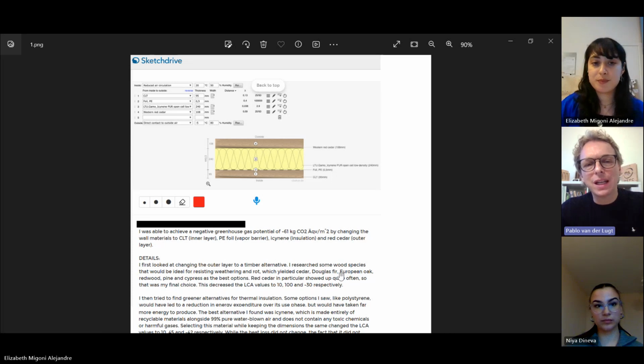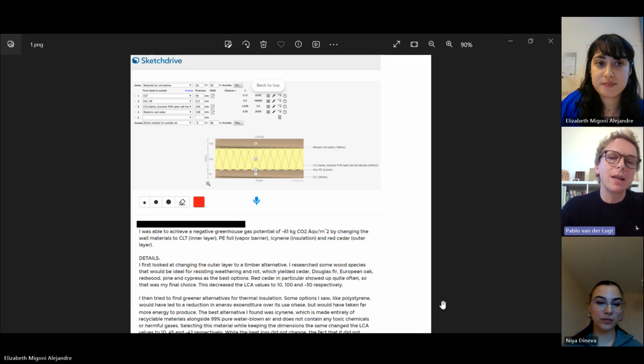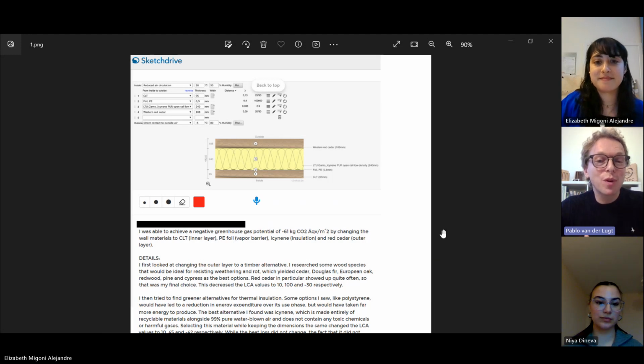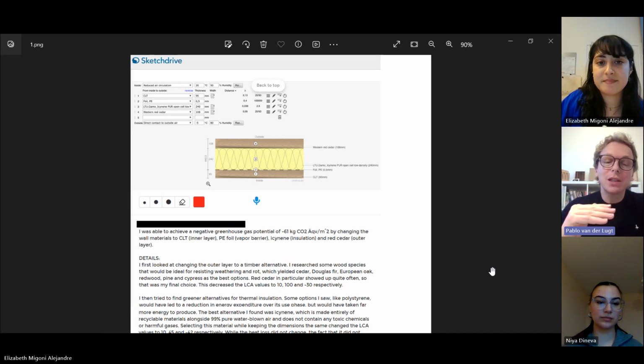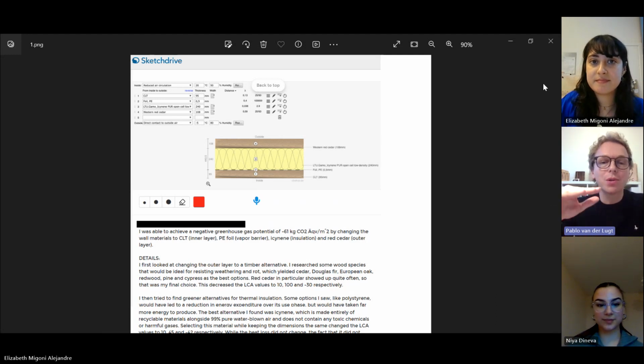And of course, you need this, and of course, it could add a little. This is also a material choice that can maybe add up to the carbon footprint. And so there are many other considerations when building up your wall or floor system. In this case, our only purpose was to show that if you replace, for example, synthetic insulation like rock wool with bio-based insulation, it can be cork or cellulose or many others, the emissions will go down and become carbon negative because of the biogenic carbon storage and the lower CO2 emissions.